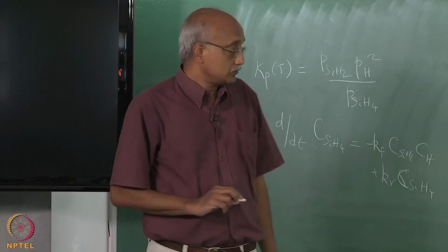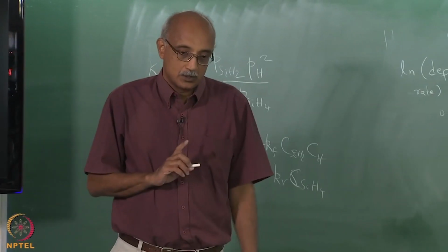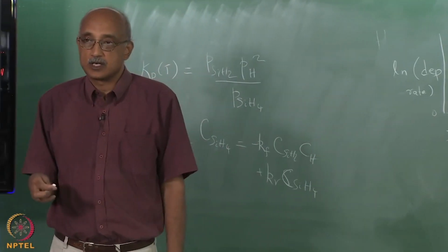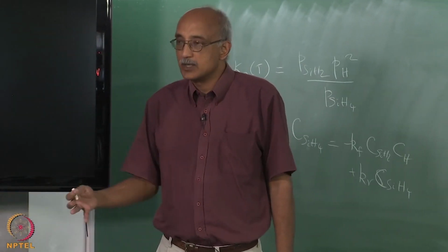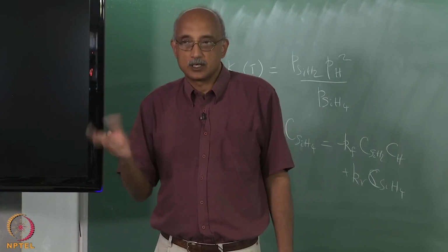Although I should mention that there is one case where you will have a reverse behavior, and that is in the very rare case where a CVD film is more favorable at low temperature and becomes unstable at a higher temperature. Obviously, in that case everything will now kind of turn around.